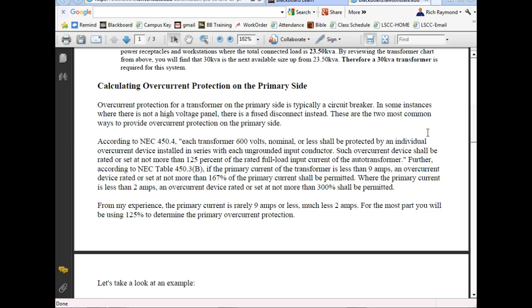This would be one of those fuses. Did I tell you about the fuse in one of our radio transmitters out at US Steel? If you checked it with an ohm meter, it would blow it because it was rated so low. This would be one of those. Most ohm meters, when you put it on the ohm scale, put out about 10 milliamps. So you would have to check this with voltage, right?